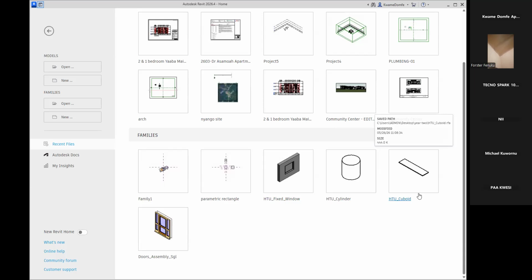You don't expect to see ridge piece or fascia in your section if you've not modeled it. You model a roof, you model fascia, you do not add the roof surface. When you take a section, how do you expect to see the surface there? You can't see it.